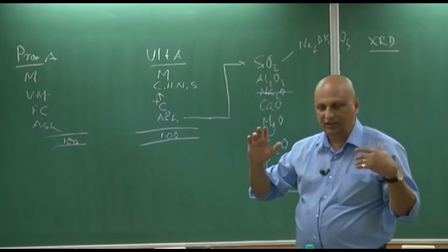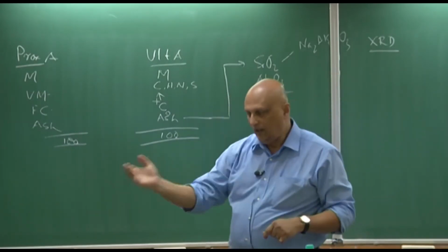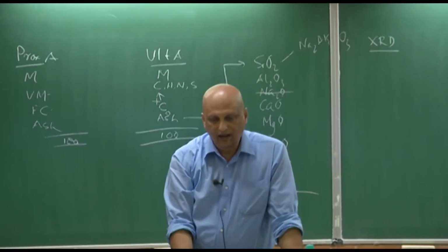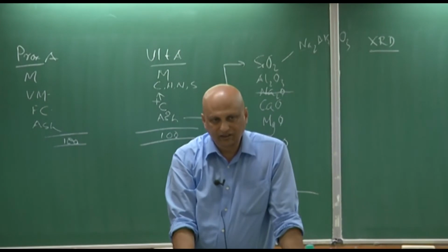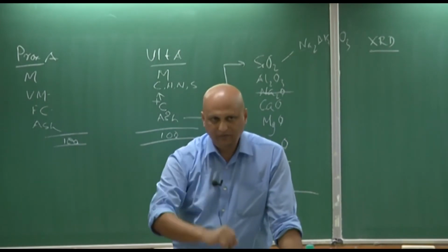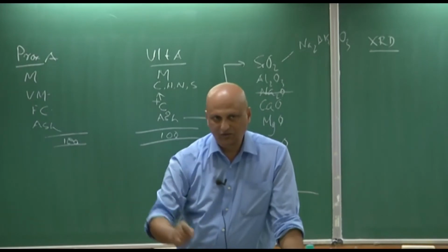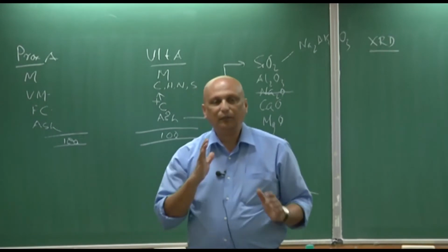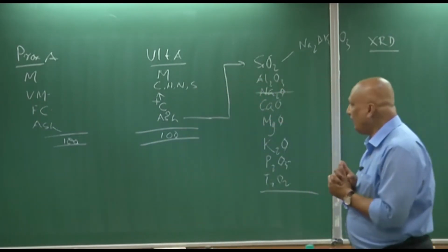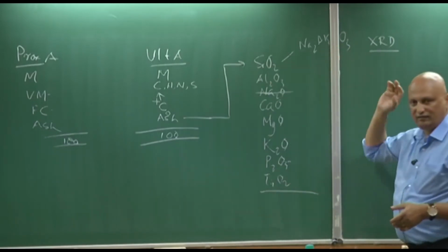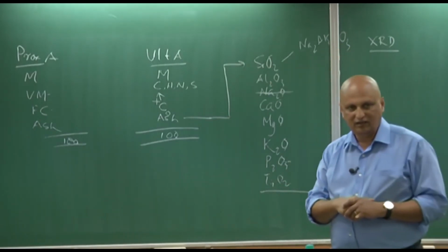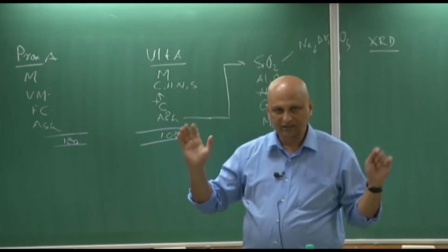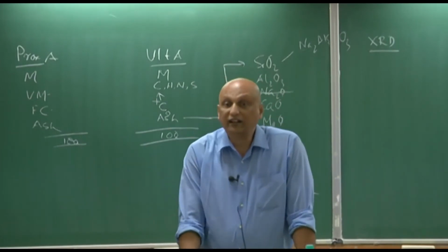But in X-ray diffraction, the crystalline compounds will come out as a sharp peak, and comparing with the library database, you can say that this is the peak for silica, and this is with my baseline. If I compare it, exactly this much silica is present, exactly this much sodium silicate is present, exactly this much sodium aluminosilicate is present. The point I am making is, all of these are measurable by complementary analytical techniques, pretty well established, and standards exist.